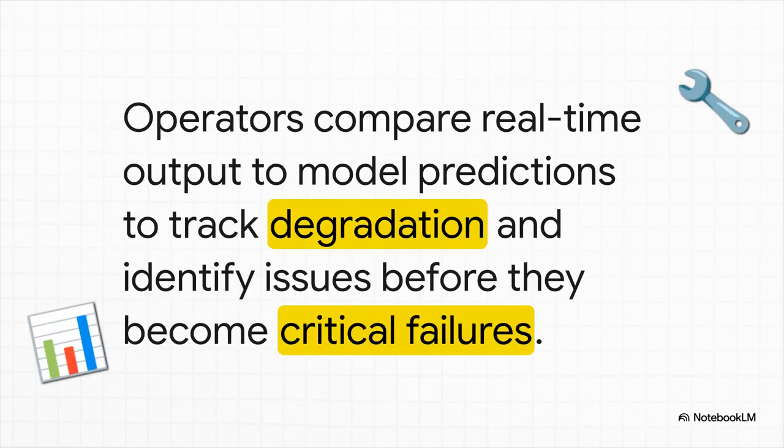Then, once the solar farm is built and running, the model's job changes. Now, it's all about performance monitoring. For any given moment, with a certain amount of sunlight and a certain temperature, the model calculates exactly what a healthy panel should be producing. So if the real-time data from the field doesn't match that prediction, alarms go off. It immediately tells operators, hey, go check this string of panels. Maybe it's dirty, maybe it's degrading faster than expected, or maybe there's a fault.